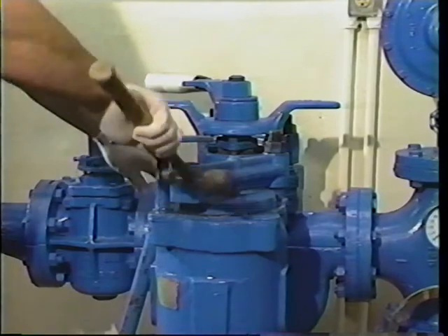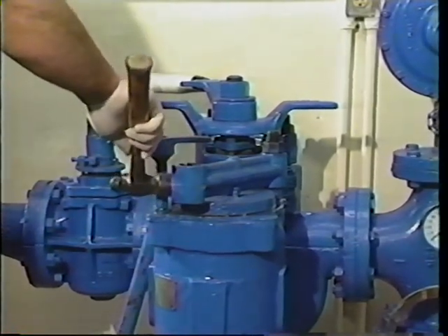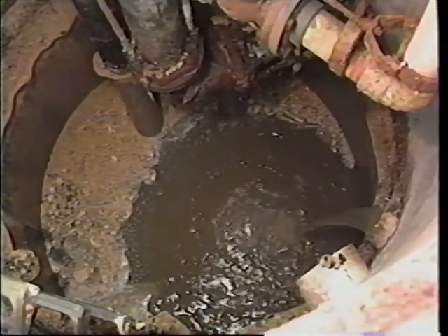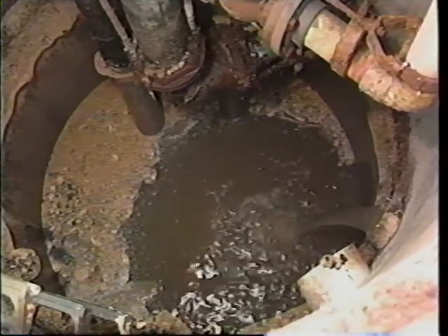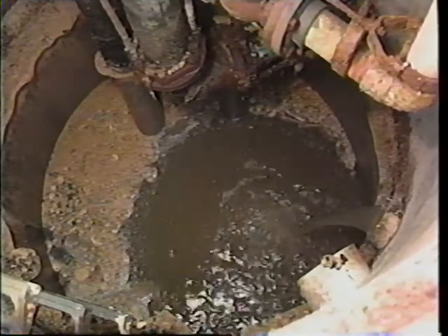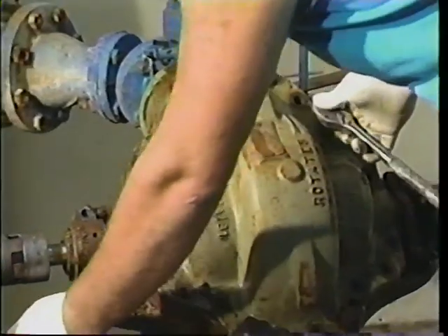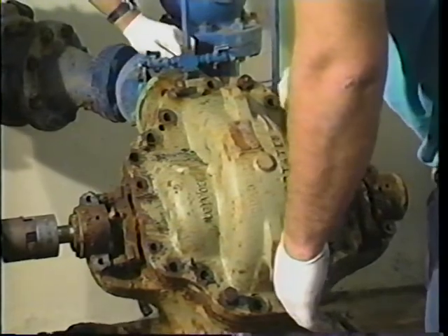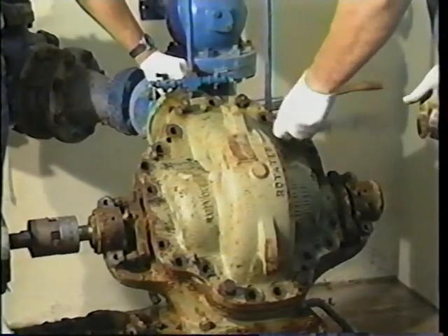Some wastewater collection systems are pressurized. In this case, each individual household or sewer user has their own pump station with a grinder pump. This type of collection system is typically used around lakes or other areas where gravity flow for sewers is difficult. This type of collection system has virtually no problem with inflow or infiltration, but can be intense to maintain with all of the pumps.